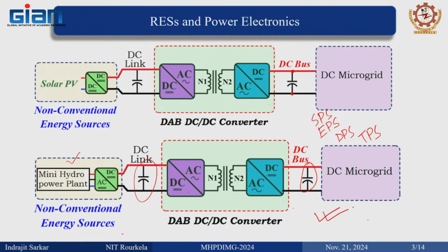Now, you can see that you can play with the angles. It is in open loop mode. In closed loop, you have to control this EPS modulation. Then the duty ratio, inner and outer phase shifts you have to control in order to control both the back power flow as well as the power flow from one side to the other side.